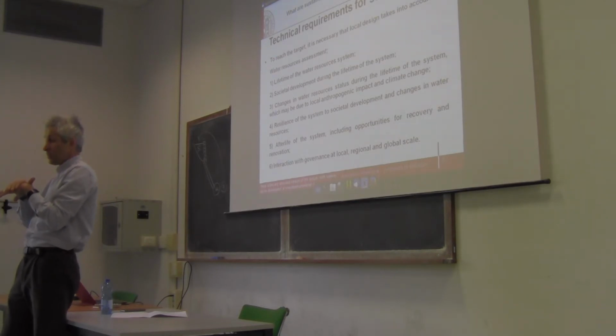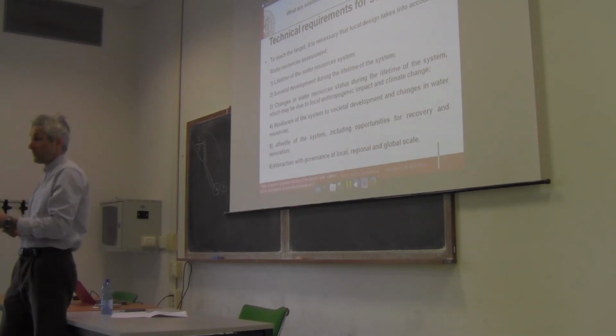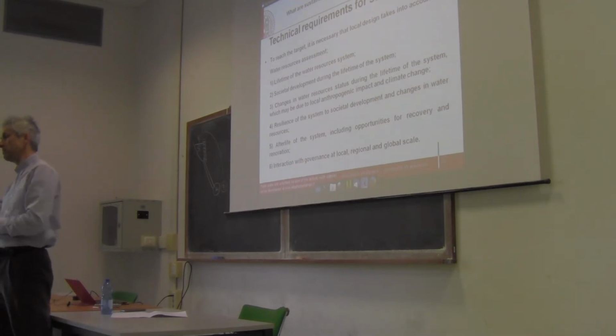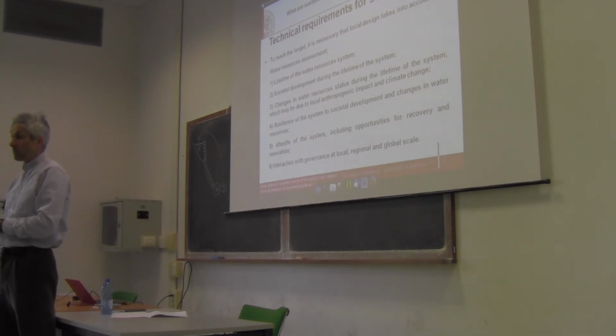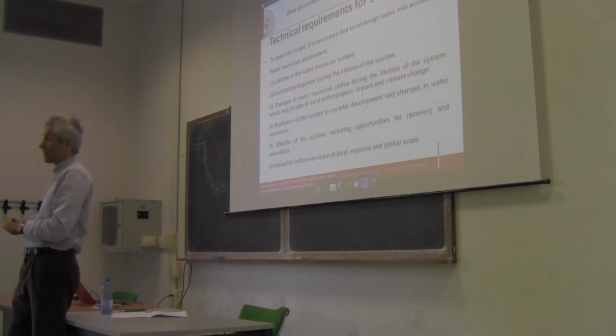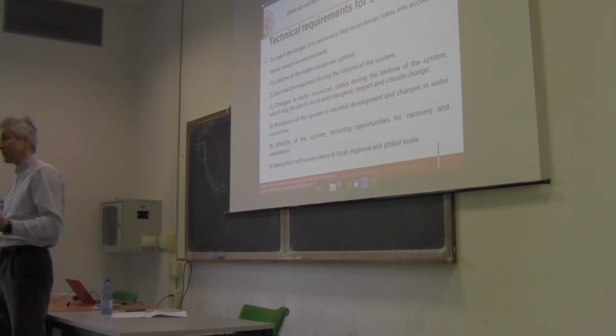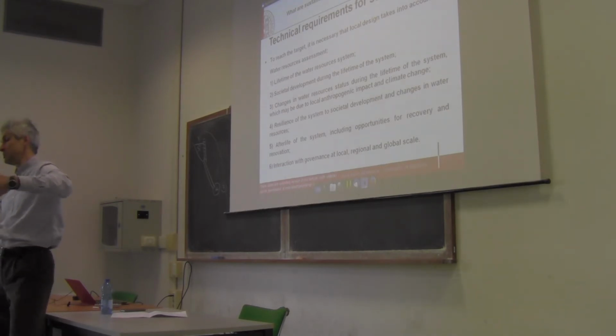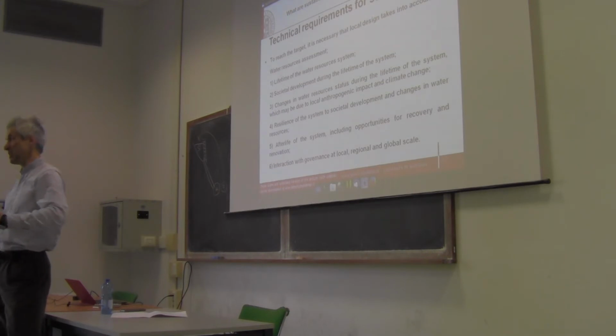In agriculture, open channel flow dominates for delivering water, but we have examples where even in agriculture you use pipes. And the reason why open channel flow dominates is that for agriculture we have to deliver a lot of water. The volume of water is very, very relevant, because we are talking about 3 times the consumption of industries. And therefore, this is why if you use pipes, in some cases you need to use very huge pipes, which